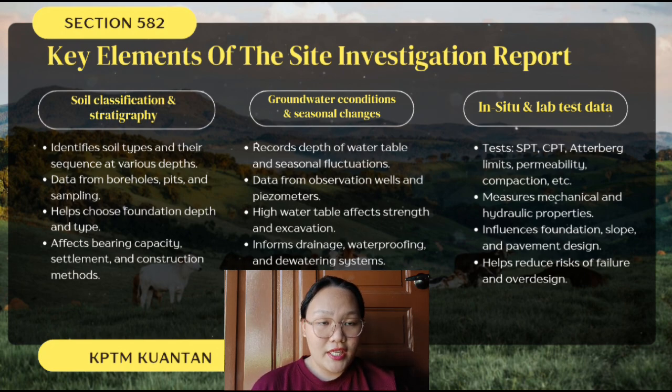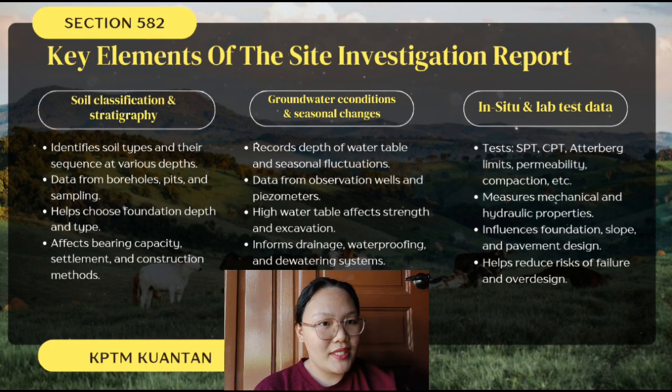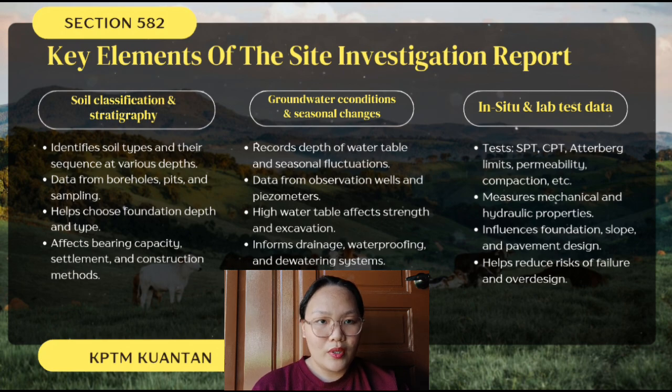Second, we have groundwater condition and seasonal changes. This part of the investigation records the depth of the water table and how it might change with the season. The data is collected using observation wells and piezometers. High groundwater can reduce soil strength and make excavation harder. So this information helps plan drainage, waterproofing, and dewatering systems.